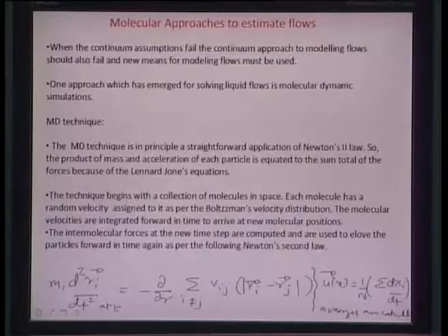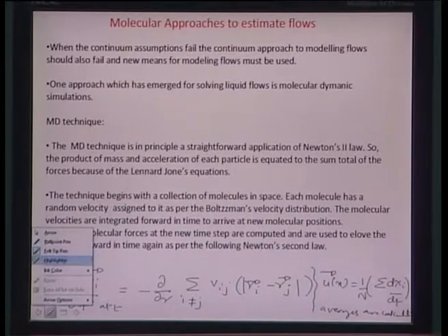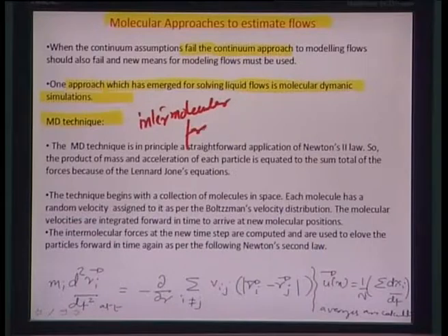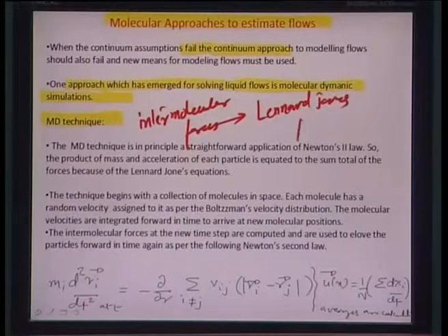So therefore, with this kind of concept in mind, let us look at what happens when the continuum fails. We would like to use molecular approaches to estimate flows, particularly when there is a failure of the continuum approach. The only other approach which has emerged for solving liquid flows is called molecular dynamics simulation, which deals with all these intermolecular forces, as I have been telling before, and which can be established from the Lennard-Jones potential model. Okay.